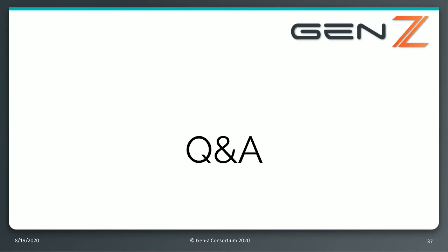It's a big mouthful of questions. So this is Steve. I'll take the question. The short answer is yes. Gen-Z chose the scalable connector form factor specifically because it was capable of 64 gig PAM4 all the way up to 112 gig PAM4, with that in mind. So the answer is yes, and then some.